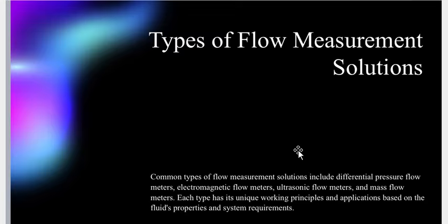Faraday described electromagnetic induction. When a conductive liquid flows through the magnetic field of the magnetic flow meter, a voltage will be generated. This voltage is proportional to the flow velocity. We can find the velocity from that voltage.